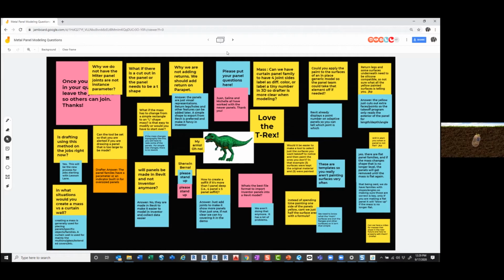I wouldn't want to encourage you to do it this way. I would much rather you use a pre-made, well-tested, battle-ready panel that's been made by Amy and the panel team before pulling that lever, because that lever is fraught with peril. There's almost zero chance that you'll get everything correct on it, and it'll definitely come back to you to add parameters to it, or you missed coloring faces or whatever. So definitely use the existing families first. And if your panel is so complicated that you do want to pull that lever, we should probably talk about it, because you're probably overcomplicating the panel.